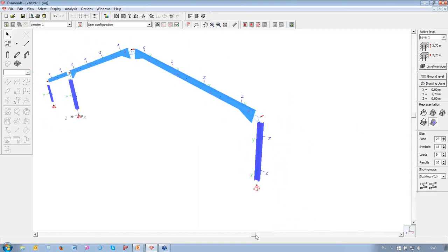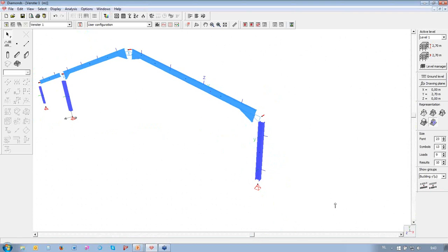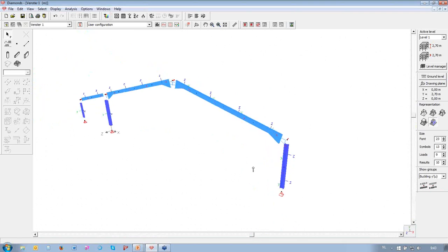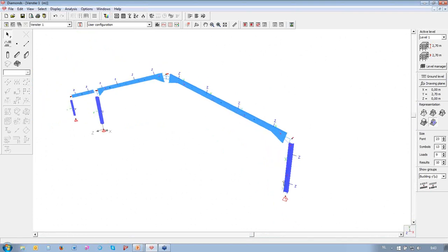So for buckling around the y prime axis, what I can see over here is that these elements are grouped together. That means that when they should buckle to the left or to the right, they are acting together as a whole, which seems logical also for these elements. When they could buckle to the top or to the bottom, they will behave as a whole, as one element. And I think for the other elements, the definition is okay.